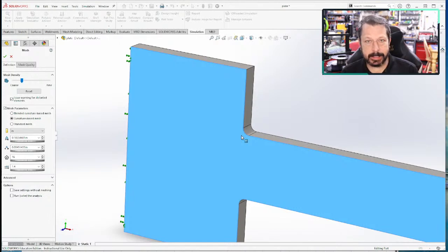What you don't want to see is, when you plot the stresses you're calculating, that the more elements you keep adding, the more out of control it gets. It explodes, like an exponential curve or something like that. You don't want to see that, because that does not give you a good sense for your model. It means you probably have some kind of singularity developing in your mesh, something like that.